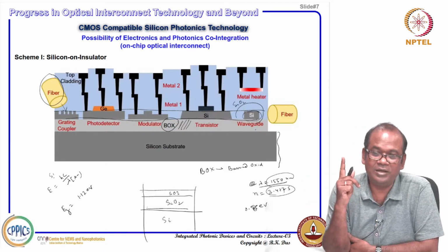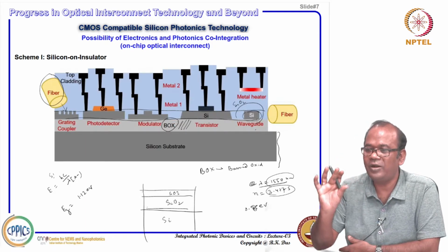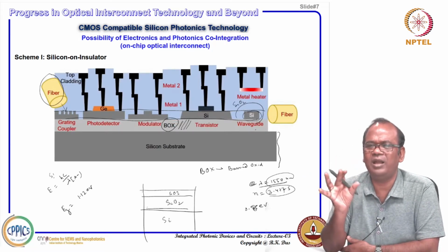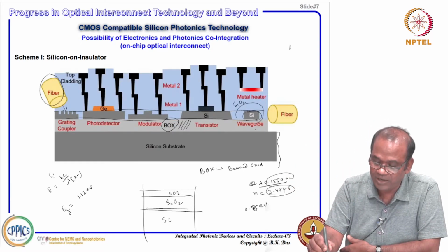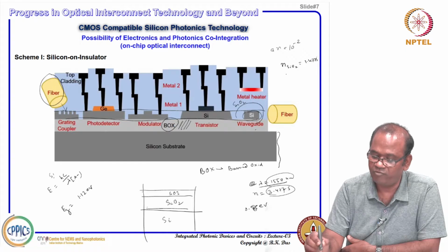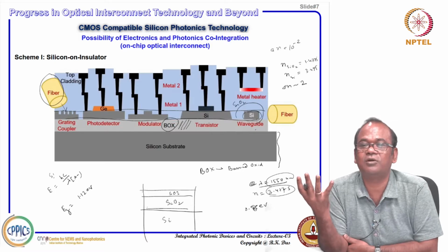You remember that when the integrated optics proposal came in, it was mentioned that if the core refractive index delta n is just 10 to the power minus 2 to 10 to the power minus 3, then you can confine light, you can make a guide, you can make a laser beam circuitry. But here n SiO2 is about 1.4775 and n Si, the refractive index for silicon, is 3.4775. So delta n is in the order of 2, a very large refractive index contrast.